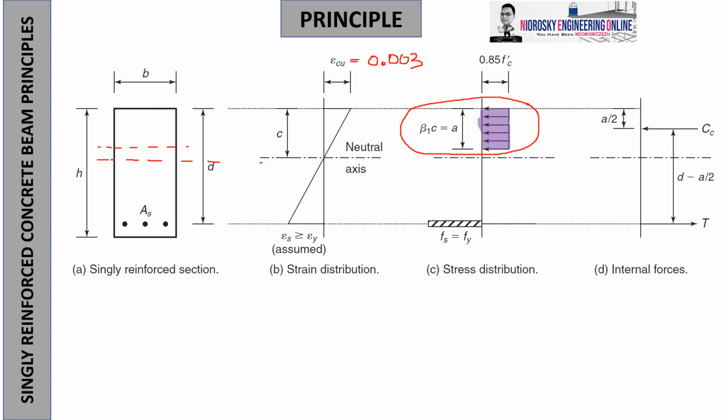So what we need to understand is the whole compression volume, the compression concrete. This is the only one we will take, shaded in violet. So we will no longer mind the gap difference between the height of the compression block and the height of the neutral axis drawn in blue. So this, let it disappear from our analysis.